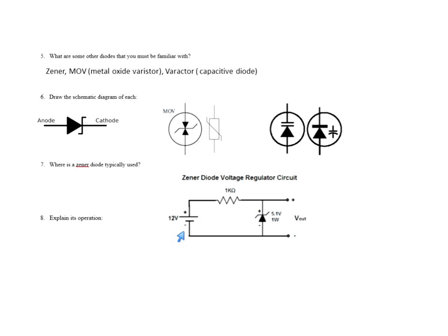You have the unregulated voltage here, and the voltage over here that you want to regulate at is the Zener voltage. There it is. This is a 5.1 Zener. So even though I'm using 12 volts as a power supply, I'm only going to apply 5.1 volts to the load, which is connected between here and here. So the Zener is always placed in parallel with the load, and it's always reverse biased.